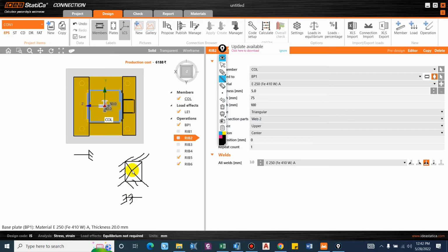So this is the general idea, that is we are reducing the effective length with the inclusion of stiffeners. The previous effective length was this, now with the inclusion of the stiffeners, this load is already transferred or taken by this stiffener, this is being taken by this portion, and this portion is being transferred or carried by this stiffener.